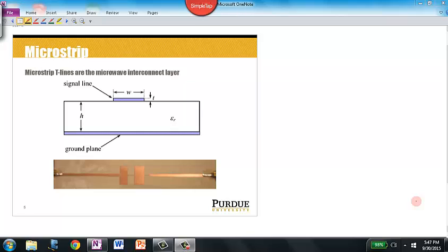At high frequencies, even extremely short wires are going to begin to exhibit a wide variety of parasitic effects. Because of this, microwave and other high frequency circuits are almost never constructed using standard breadboarding methods such as through-hole or the proto boards that you're used to using in the labs.